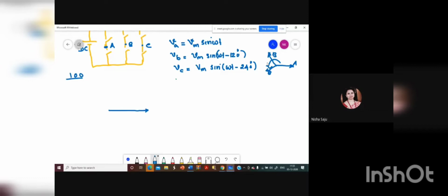And here also, if you are considering the 1 0 0 state, you have to find the resultant of 1 0 0. A is the top switch, B and C are the bottom switches, right? You have to draw the three switch patterns because it is a three-phase system. This is your A phase, this is your B phase, and this is your C phase. Then A is turned on, 1, so you will be getting the pole voltage with respect to the bottom part.